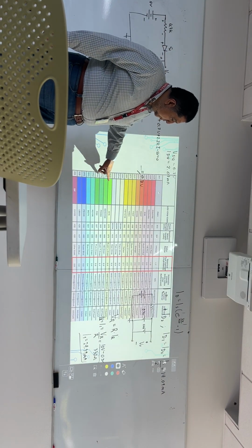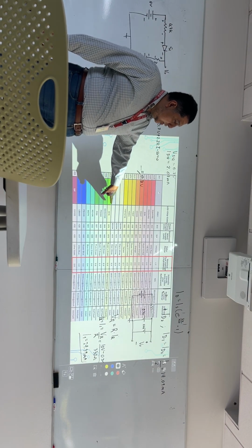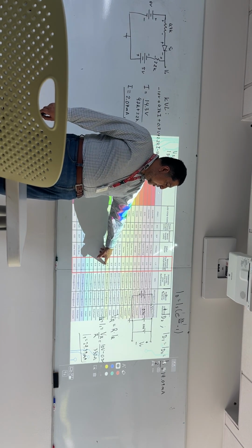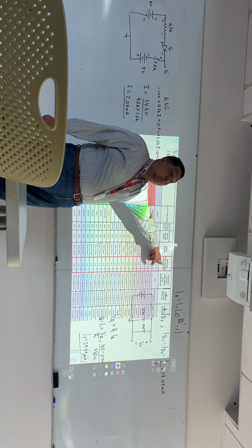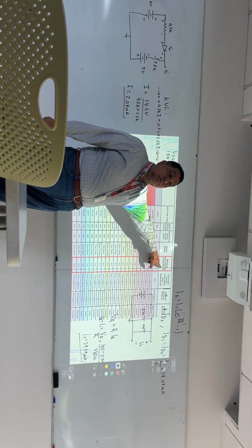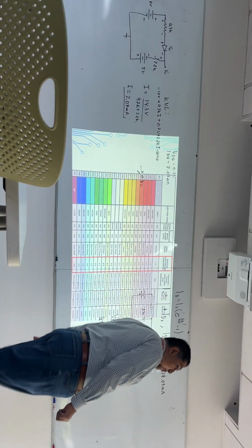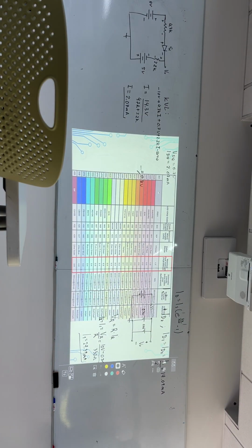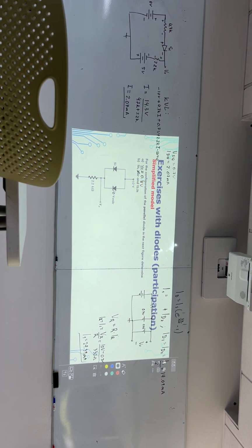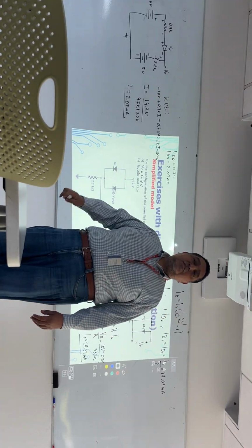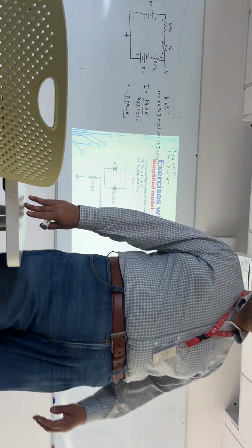So right now we are going to consider the super green LED since it is easier. So please consider that the VF voltage at 20 milliamps is 2.0 volts. So we will go back to the circuit. Now the activation voltage is 2 volts. For silicon it's 0.7. So now you are able to solve the rest of the problem.